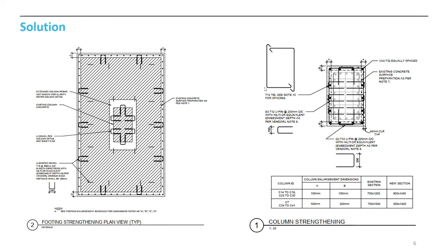This is always a topic of debate. My perspective is that I have been asked to strengthen columns in buildings that are completely built, and then they find out they have low strength concrete. I'm curious if you had any thoughts on shear friction, as you're checking the provisions of ACI 318 for shear friction when you're trying to share load between those two pieces of concrete.